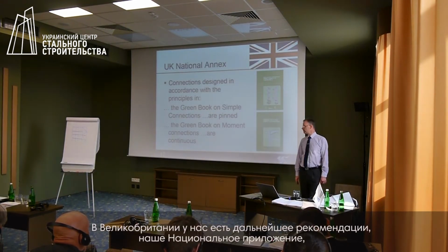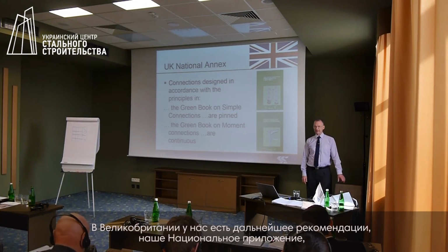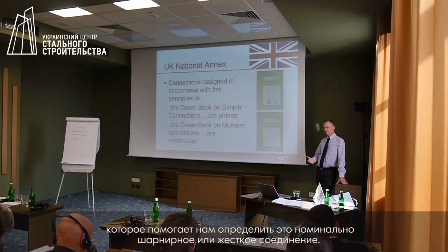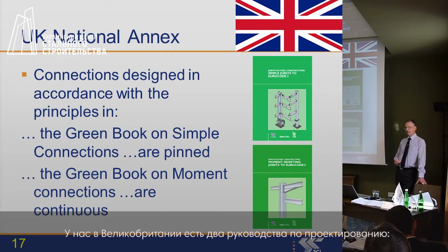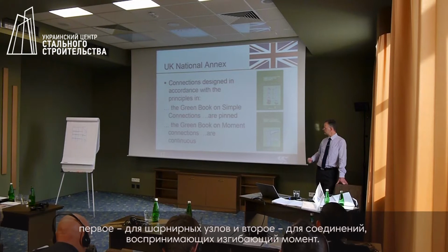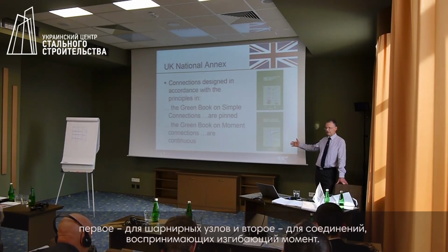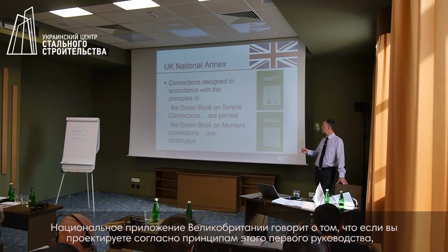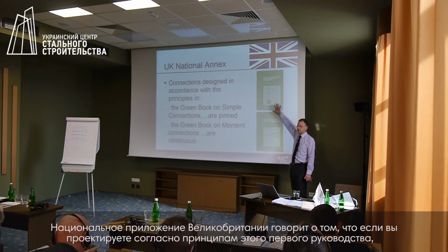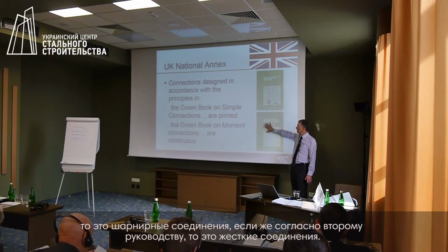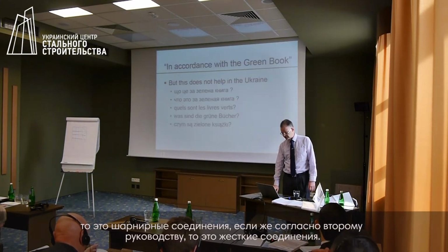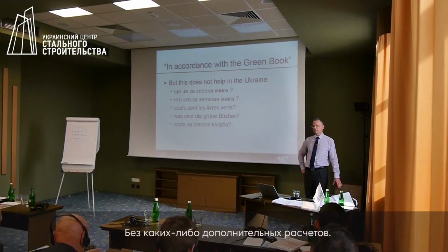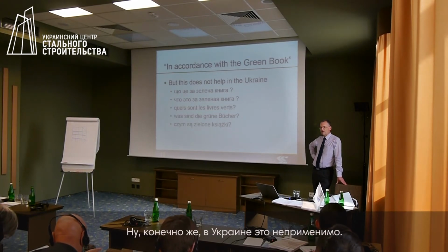In the UK, we have some further assistance because our national annex helps us to decide if our connection is a nominally pinned connection or a nominally rigid connection. So we have two design guides in the UK. The first one covers nominally pinned connections. The second one covers moment-resisting connections. And our national annex says, if you design in accordance with the principles in this one, they are pinned. In accordance with the principles of this one, they are rigid, without doing any calculations. But clearly, that has no contribution in the Ukraine.